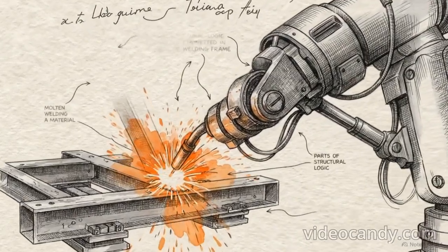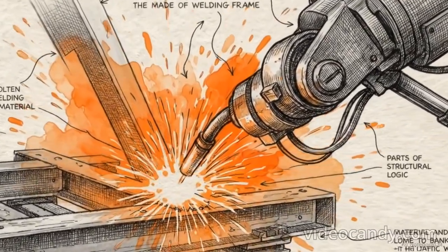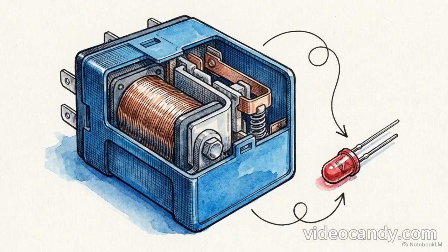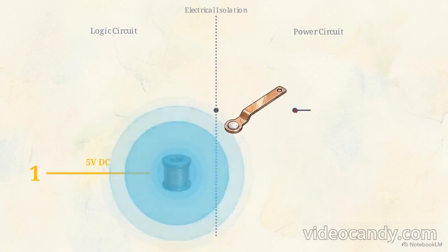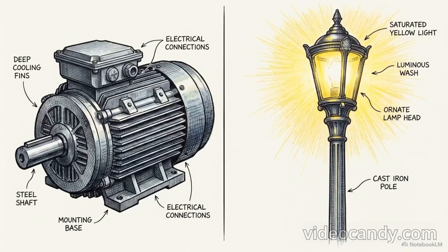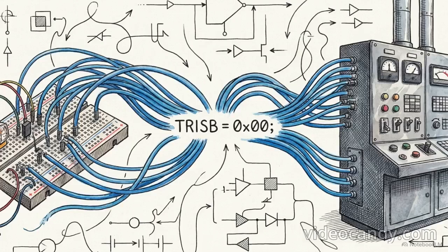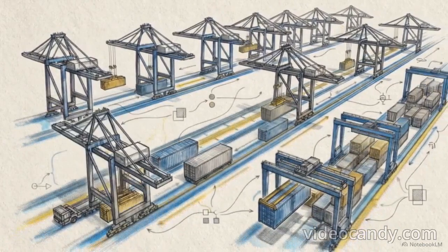While blinking 5-volt LEDs on a laboratory breadboard is a straightforward visual aid, this exact same microcontroller architecture scales directly to heavy industrial applications. Instead of connecting a tiny light-emitting diode, you can connect the output pin to a 5-volt electromagnetic relay module. Pushing a 1 to that port pin now triggers the relay coil, allowing the system to switch 230-volt alternating current loads. This means the chip can drive heavy industrial motors or actual municipal streetlights. The C firmware, the TRIS initialization sequence, and the state machine logic remain completely identical, regardless of the size of the physical payload. Navigating the memory-mapped architecture of a microcontroller provides the framework used to automate control systems across the physical world.